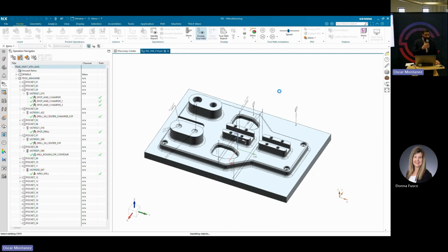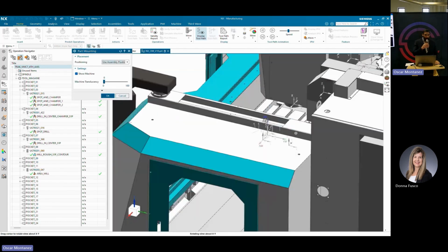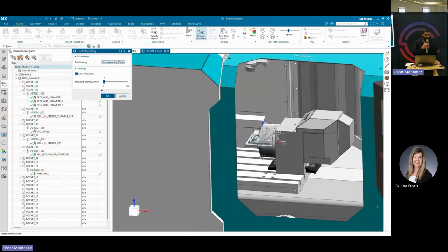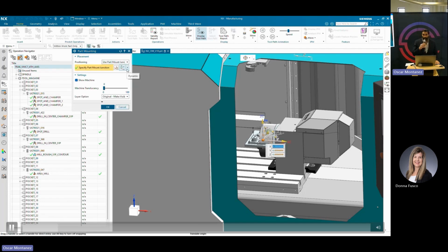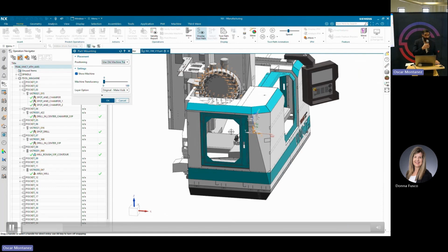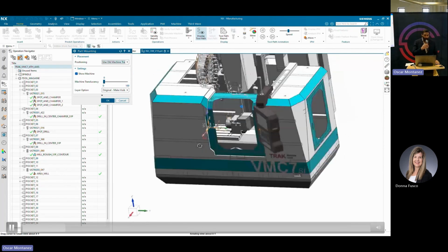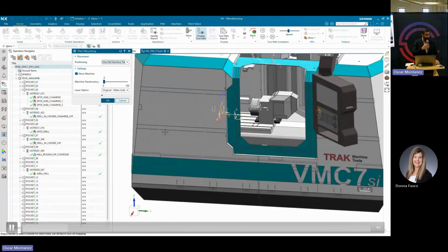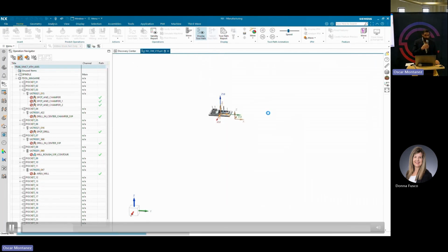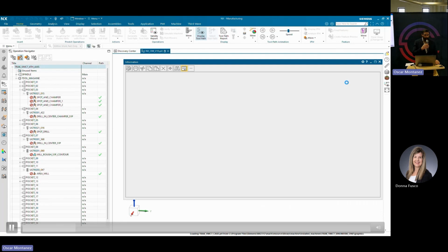And what that entailed was loading up my machine, loading up my tools, and then coming up with a roughing operation, a rest machining operation, and then a semi-finishing operation. And I just left it at that. What you're seeing now is me pulling in the machine. And actually, I just set up the part roughly where it's going to be located on the machine there.